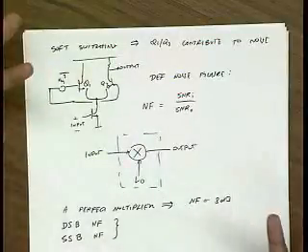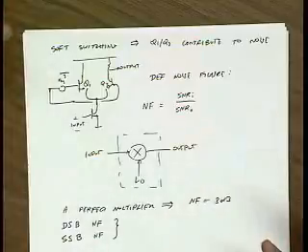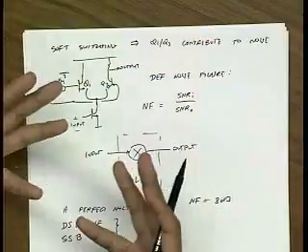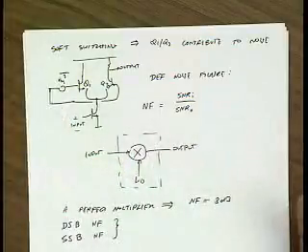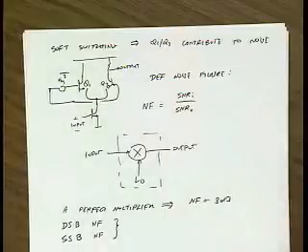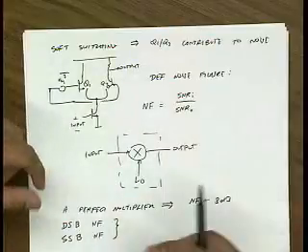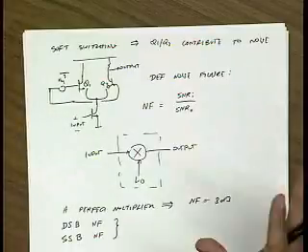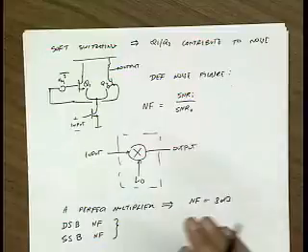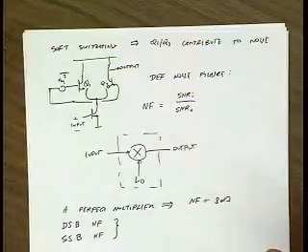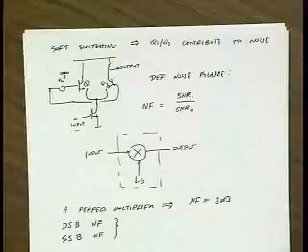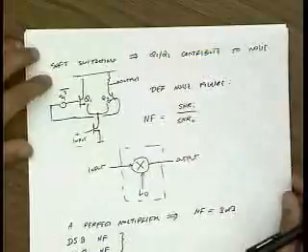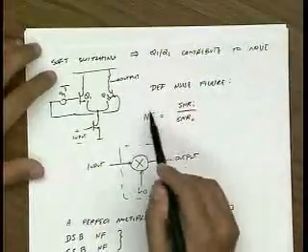So there's modulation in the image band, in which case, if you go through even a perfect multiplier, you get noise from the image band, but you also get signal from the image band. So the noise figure again would be 0 dB. Single sideband noise figure, on the other hand, assumes that there's only information on one band and noise on the other. So single sideband noise figure is either a minimum of 0 dB with the IEEE definition, or 3 dB with the non-IEEE definition, let's say. And unless stated otherwise, you can assume that this is the noise figure.